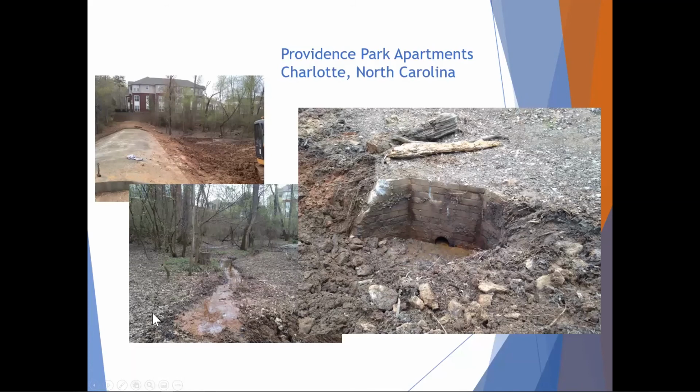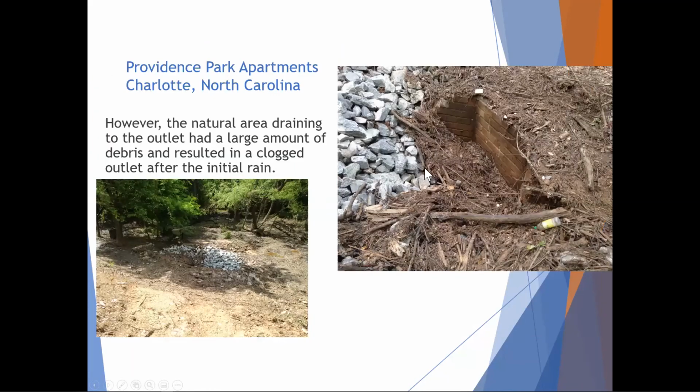We had another site in the Charlotte area, an apartment complex, that had a really old pond that had not been maintained in a very long time. We helped them clean it out, found it had a head wall down here, it had a pipe down at the bottom that when we started, the mud level was up to nearly the top of this head wall. It took us a while to even find the outlet just because it hadn't been maintained. But we got that cleaned out, and we added some riprap around it.